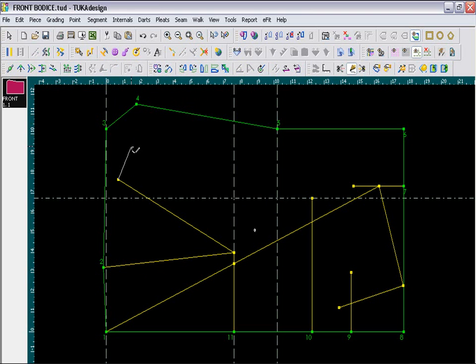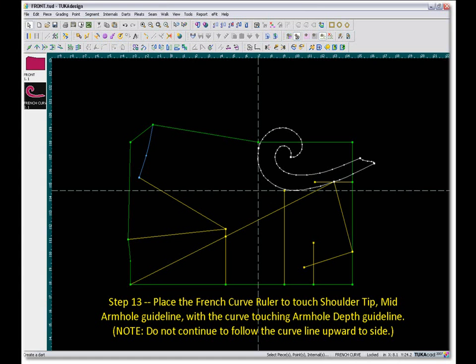And then I go back to draft tool and I can then draw my segment. Here I'm going to draw a curved line, so I hold down the shift key to get my curve point. I just need a slight curve. You can always take the move point tool and adjust your segment. I also need to put a curve point here, so again, holding down the shift key, just give a slight curve at the bottom.